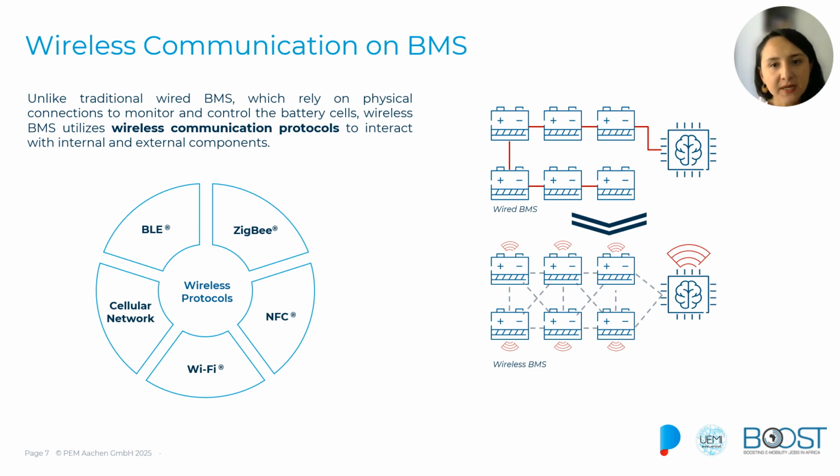Okay, so wireless battery management systems, it's a new trend that is evolving very fast. And basically with these trends, we are changing the way that we manage and we monitor the battery packs. Traditionally, the BMS units connect the sensors and all the hardware that is connected to the BMS, all of it is connected via wired harnesses. However, the wires will add some weight to the battery, and this can be challenging to install also, and at some point will add some vulnerability to our system.